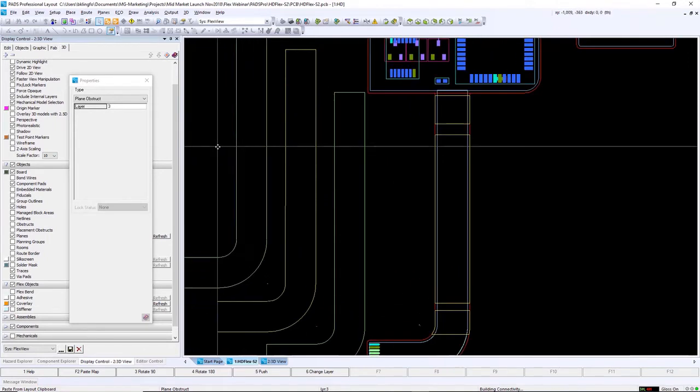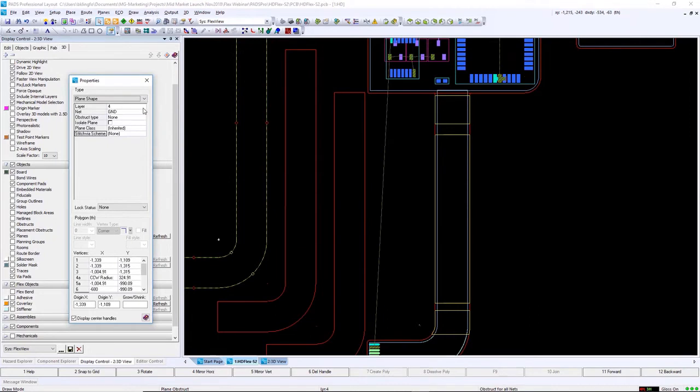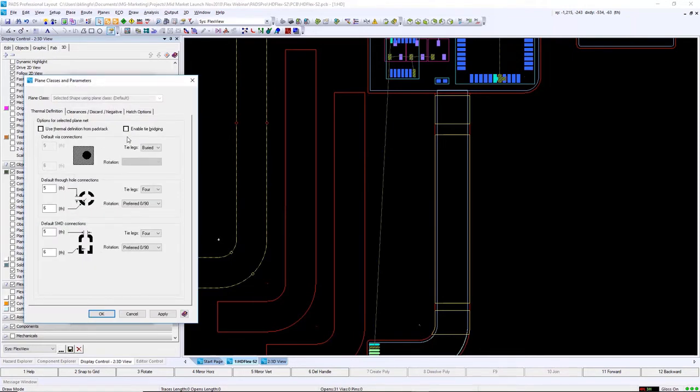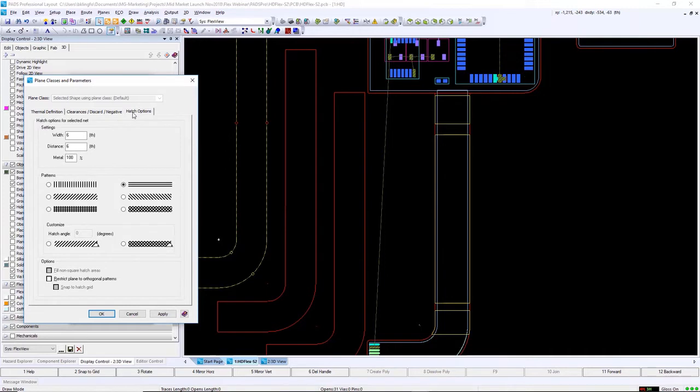When bending a flex, having unequal copper area usage on adjacent layers can lead to higher failure rates. So for our ground planes, we need to crosshatch the copper. To follow best design practices for flex circuits, plane areas should not be created using orthogonal hatching. They should be diamond hatched so that you don't end up with the I-beam effect with traces on adjacent layers.